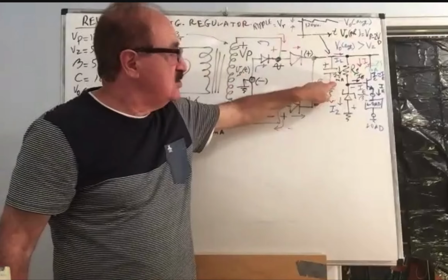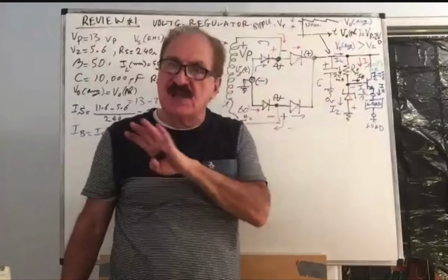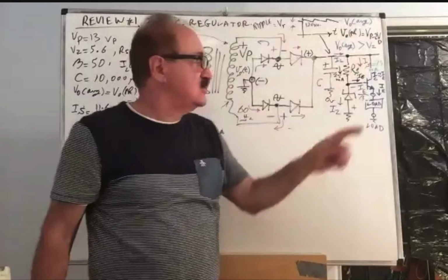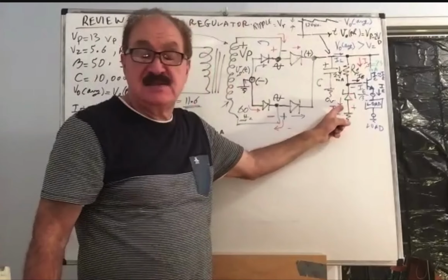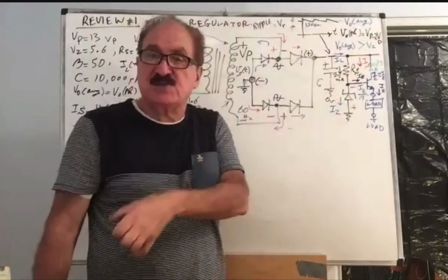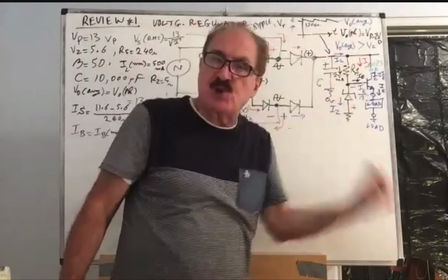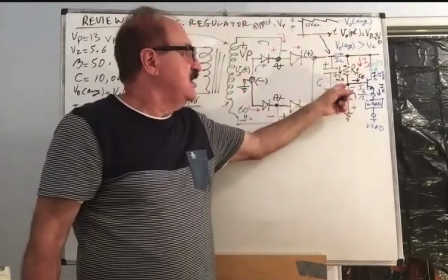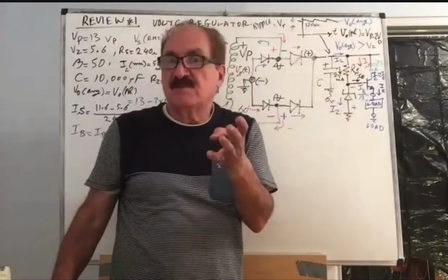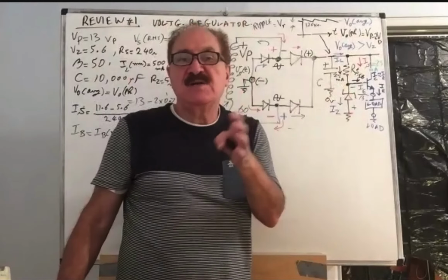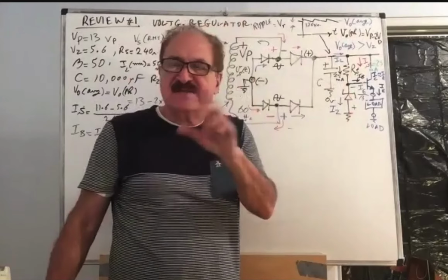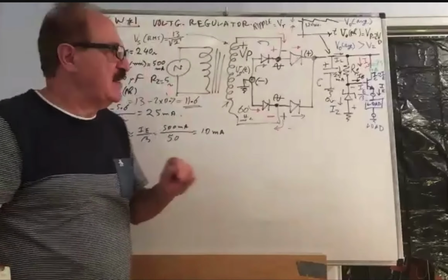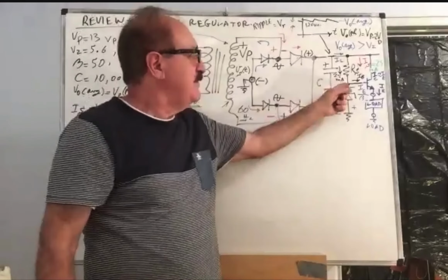Incidentally, this 25 will permanently stay 25 as long as the current in the Zener is not violated. It's not depleted. It's not withdrawn completely. You leave something in the Zener. Limit is actually IZ max about 5 milliamp. Sometimes 2-3 milliamps. It just depends. So imagine how much we could go.